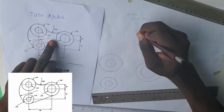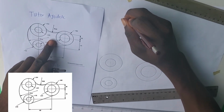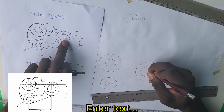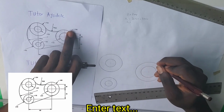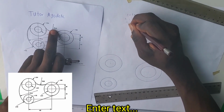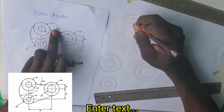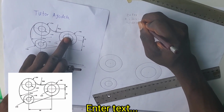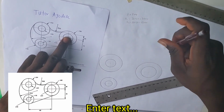Then for this other part, you are going to have E2. The given radius is 32. Remember, the given radius plus the radius of this circle, which is 30. That will give us 62 millimeters. That's what we are going to use to draw.